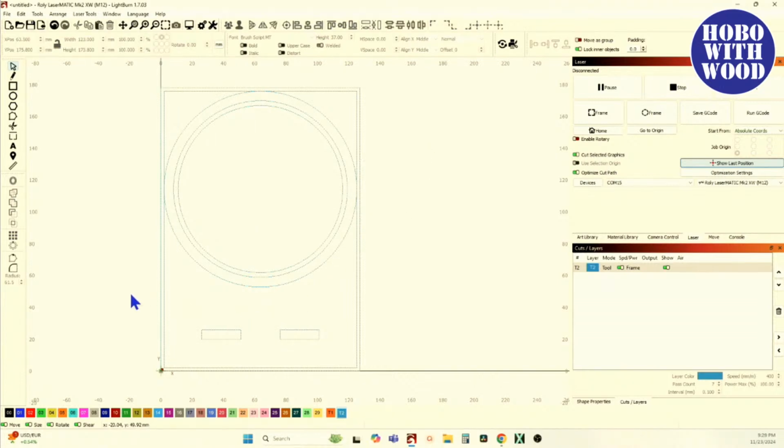Now I need to make a base. So if it's 6 millimeters wide, I'm going to draw out a rectangle. Not sure about the dimensions yet because I've got to figure it out. How wide is this one right here? This toolpath is 123 wide, so I'm going to say 123 wide. Go ahead and put it in the center and put it at the bottom. Then I'm going to change my anchor point to the bottom center. Now, how high does it need to be?